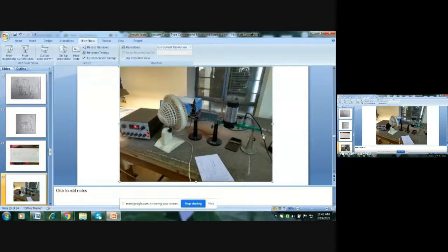And this DC power is measured by the indicating meter, or we can directly measure the power at this point if you are having a power meter. And this deflection is proportional to the input power, because this diode converts the RF power into DC power, which is proportional to the input power.